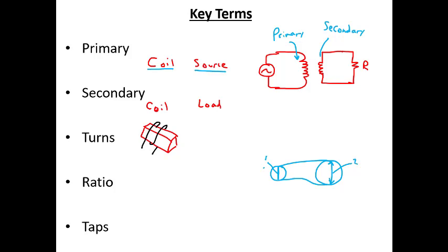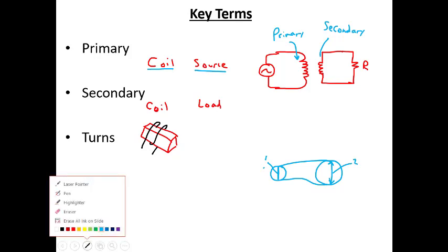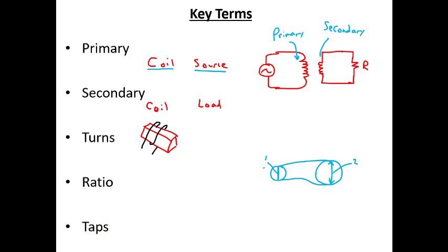So if I turned that wheel one whole revolution, the other wheel would go about halfway around. I'd have to turn this one around twice to get this one to turn once, because this one has twice the diameter. So we have to turn this one 2 times to get this one to turn 1. This would be a 2-to-1 ratio.